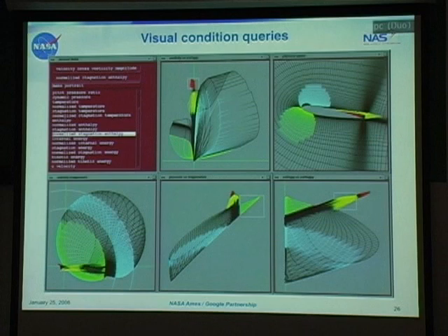Here's a little more readable version of that. In the upper right, you can see this is a data set. This is a section through an airfoil. And so there's a mesh wrapped around this airfoil, and the flow Navier-Stokes equations are being solved on that mesh. So at each point in that mesh, there's a whole bunch of other variables, like velocities, pressures, entropies, and so forth. So we can take that mesh and actually embed it in these other spaces.